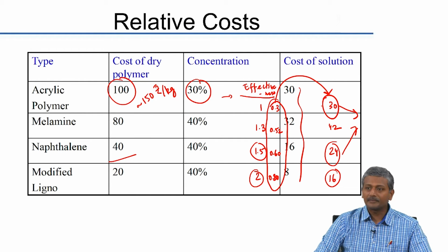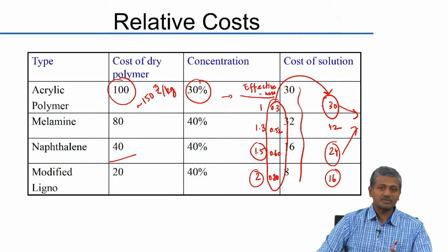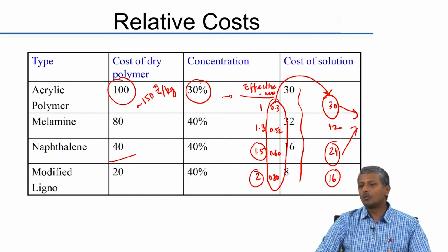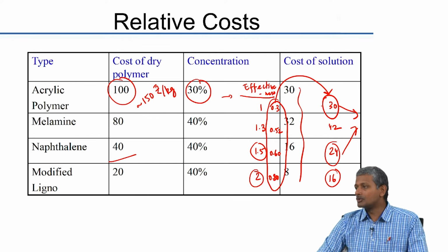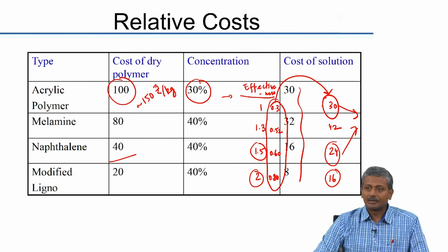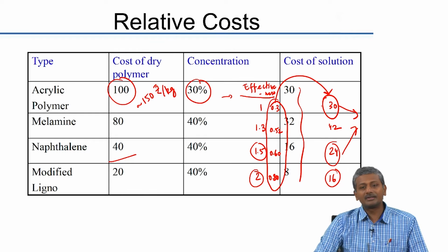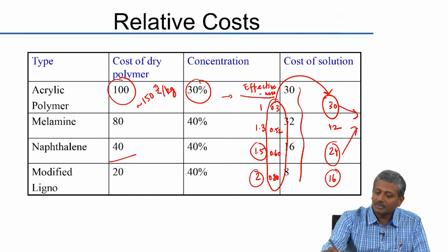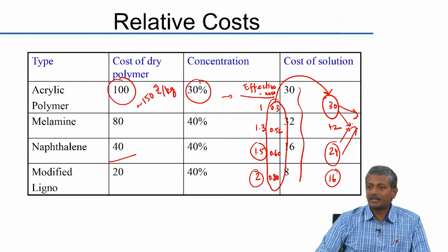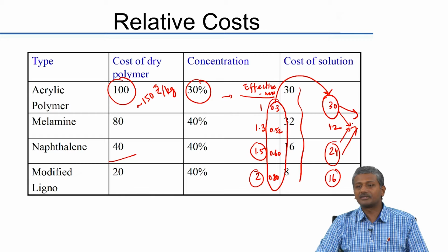Maybe yes, definitely. And later I will talk about the range of water cement ratios over which these admixtures are actually effective. What you will see is when your water cement ratio starts dipping to below 0.4, the effectiveness of the SNF sharply declines. SNF needs about 0.4 water cement ratio or more to be effective in concrete. So, if you are looking at less than 0.4, the effectiveness of the SNF starts coming down significantly. So, at that stage maybe the difference may not be that large anyway. The 6 rupees will further come down to probably 1 rupee or 2 rupees at the max.